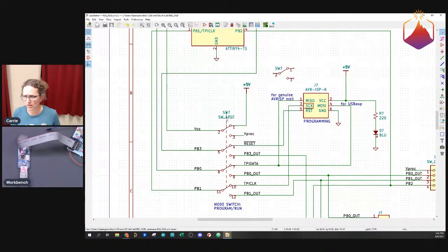So a few things are going on here. I have this big switch. This is one part that has basically 4 different lines in it that are all switched together with one switch stroke. That's called a 4-pole dual throw switch. You have 4 lines that you're switching, and you have 2 positions that the switch can actually be in, 2 signals that it can switch between.